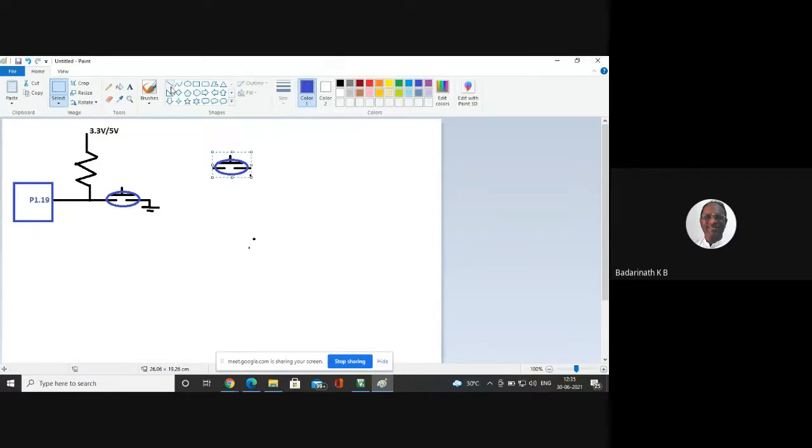When I say stable, this point should give me a perfect voltage when I read it from the microcontroller, either a 1 or a 0. It's not like sometimes 1, sometimes 0, without my knowledge or the expected way. Then it's called unstable.